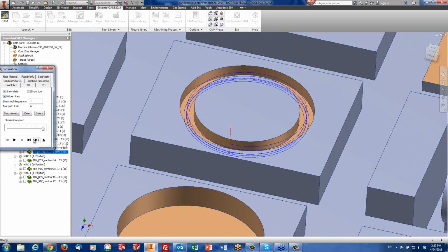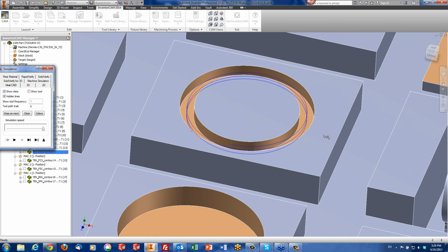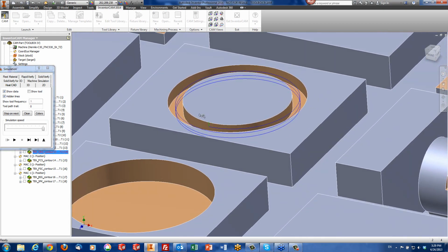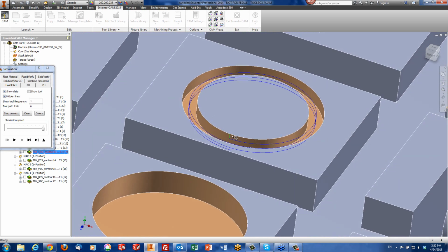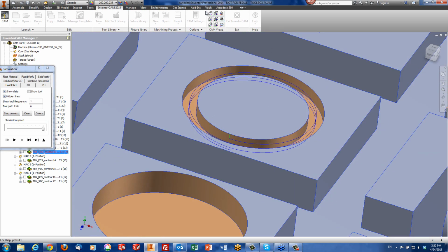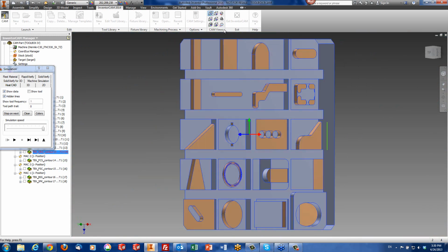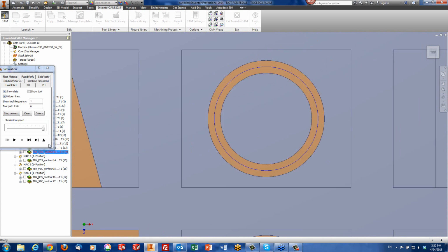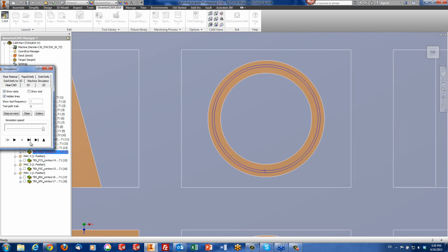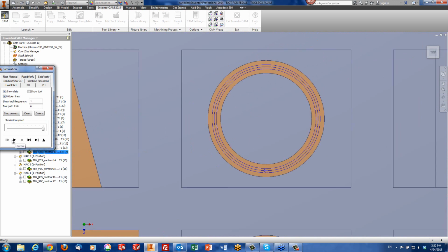You'll see that the tool goes down, and it goes down actually with a helical movement. Not going up once, but keep on going helical to the bottom. And this is through the dead center of the tool, as shown over here. Everything's dead center. Continuing on now, we start moving off to the sides to complete this entire operation.